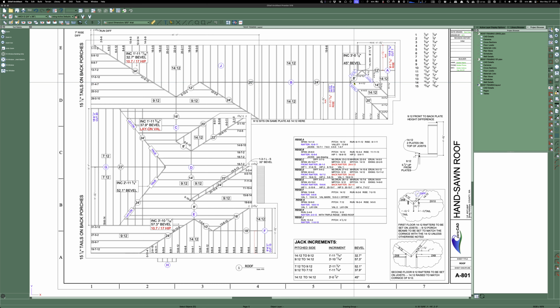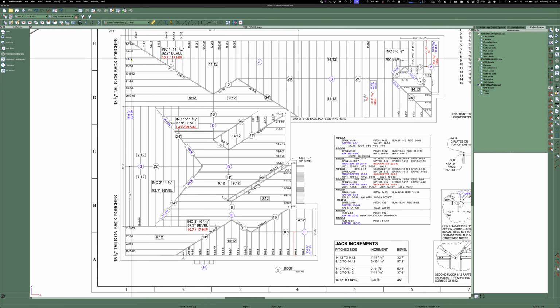And then you could tie in and put the hips. And so you get all the ridge and hips and valleys and skeleton up. And then I can go around and count what you need and cut them all and lean them up against the building. So the guys up here never slowed down. They were always putting stuff up. And then I'd start cutting all these jacks and stuff. And when they were ready, we would figure out how to establish this ridge and tie it together.